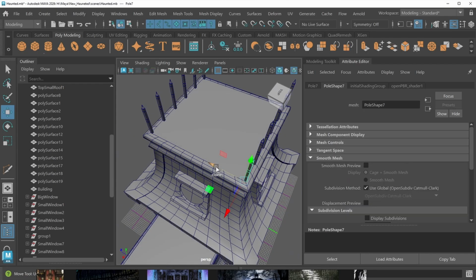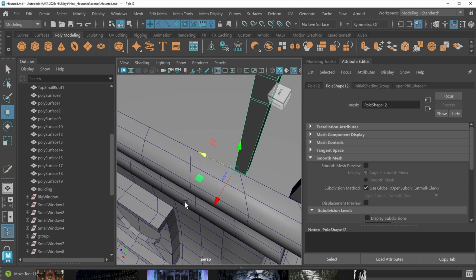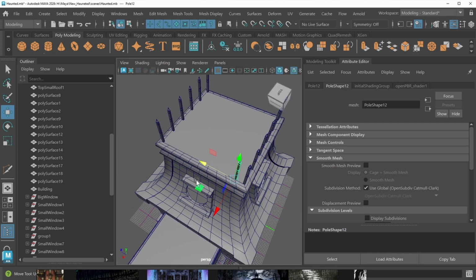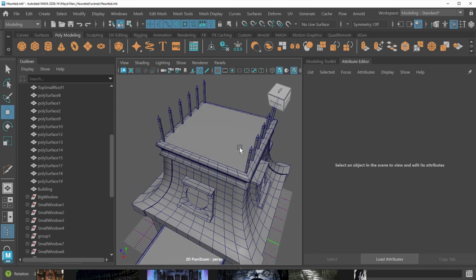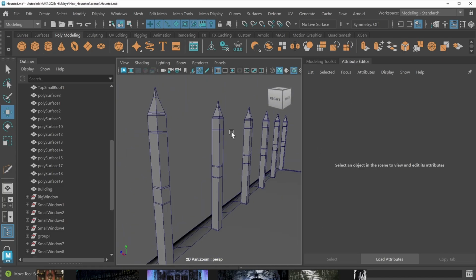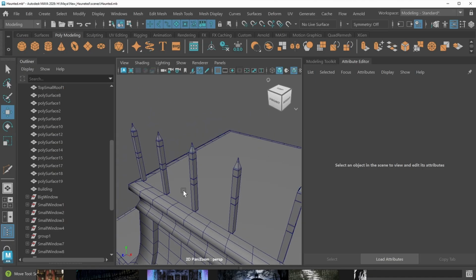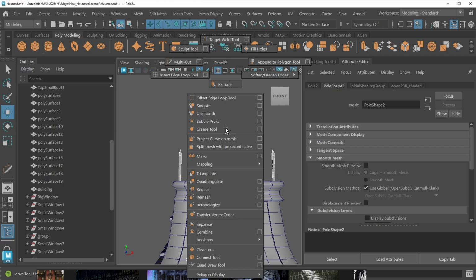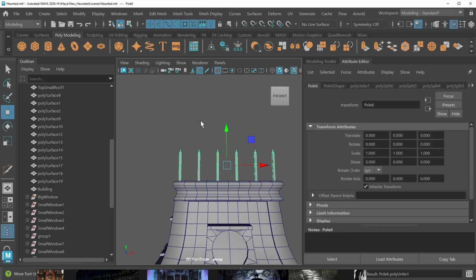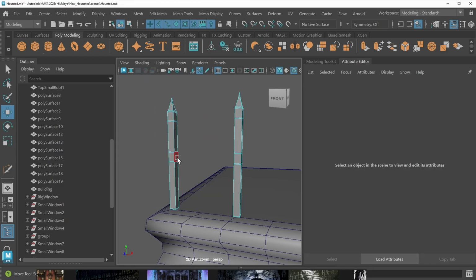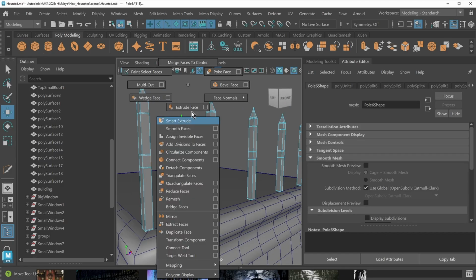So now I want to take these and duplicate. Go about here. Actually, probably what I should have done here is, otherwise I have to do multiple here. The reason I'm deleting them is because I want to connect these with the poles here. So I'm going to select these, and then what you have to do for the bridge here, go down to combine, and then in here now, all you have to do is grab this face and this face and bridge.